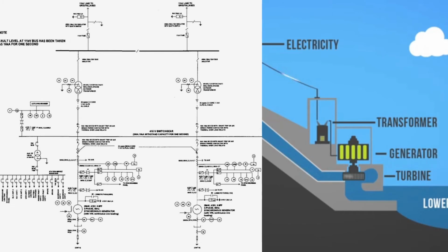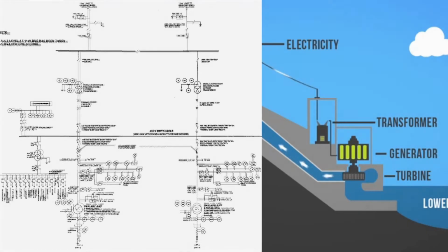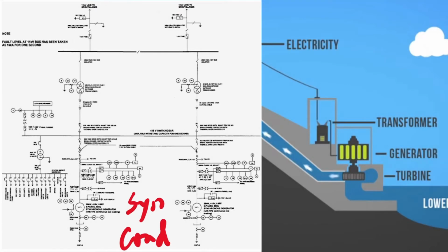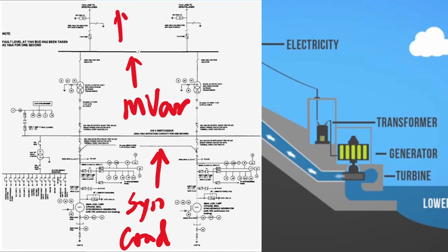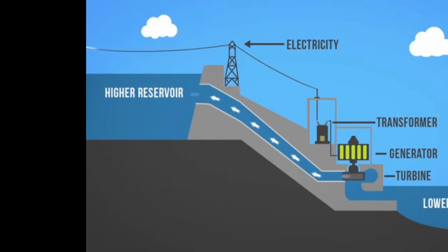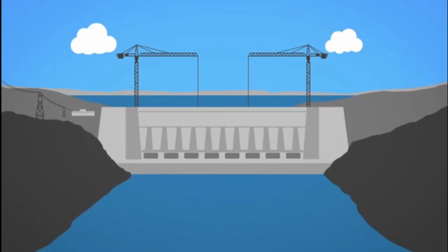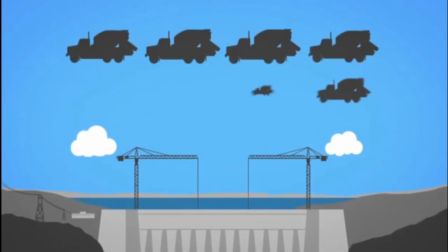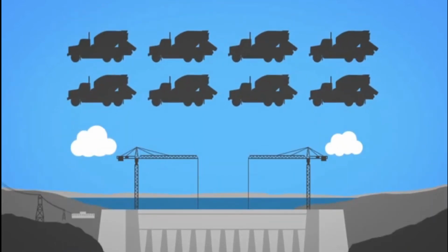The advantages of hydropower plants are that it is clean energy with low production cost. The resource is adaptable to changing demand. It can be used as a base or peaking power, with a quick start within 1 minute. Also, it can be designed as a synchronous condenser to provide MVARs, has relatively simple operation and maintenance, and a high efficiency, usually at 80 to 85%. The disadvantages of hydropower plants are that it needs large capital cost for civil works. It has a relatively low capacity factor, ranging from 15 to 50%, and the water inflow is not predictable.